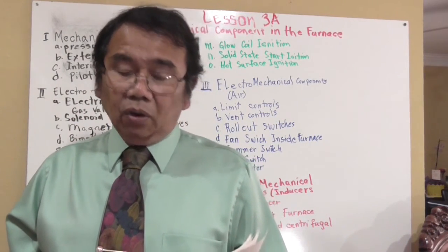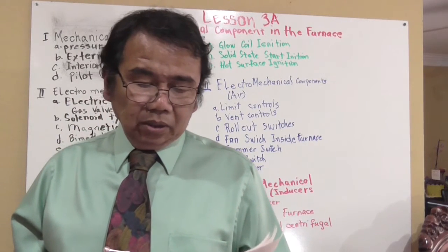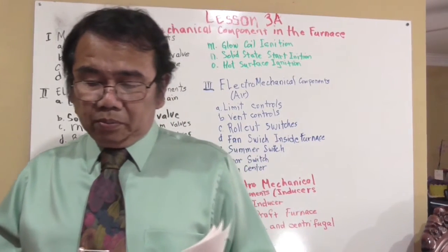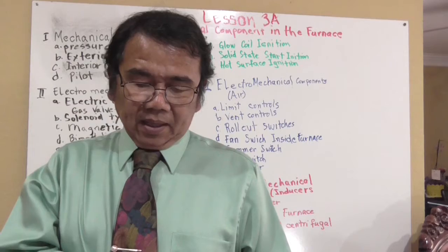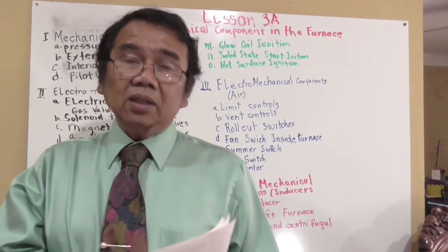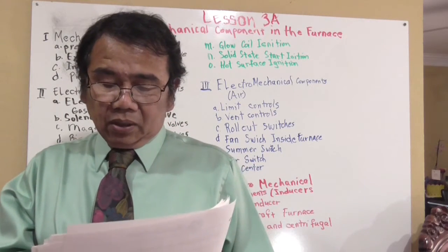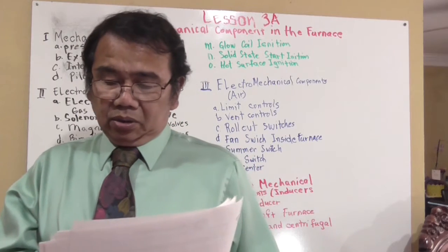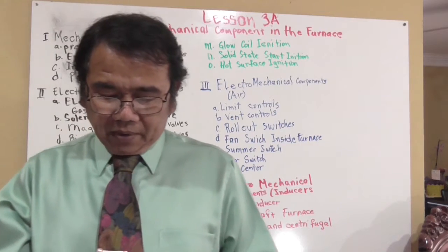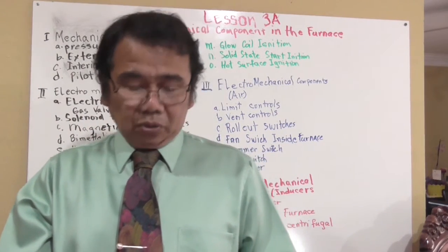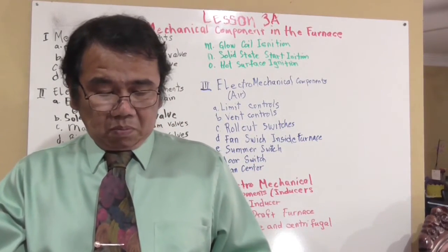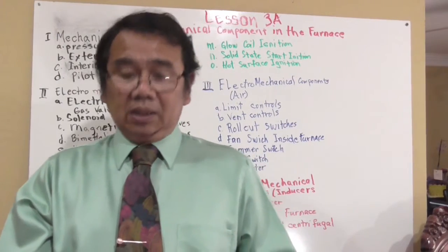When the thermostat calls for heat on the induced draft furnace, the W wire from the thermostat does two things. It energizes the coil on the inducer relay to start the inducer. The W wire also runs through an inducer proving device. The inducer proving device is either a centrifugal switch on the end of the motor or a pressure switch mounted somewhere on the furnace.